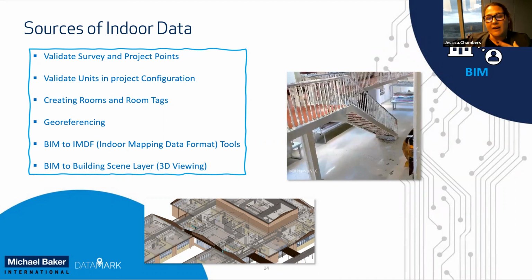Okay, so having BIM standards from an organization isn't enough. We have to make sure it is in some type of standardized format to translate the information efficiently from BIM into an ArcGIS Indoors environment. So in the marketplace right now, we have seen Autodesk come out with a connector. This connector produces and connects IFC data into an ArcGIS Indoors environment.